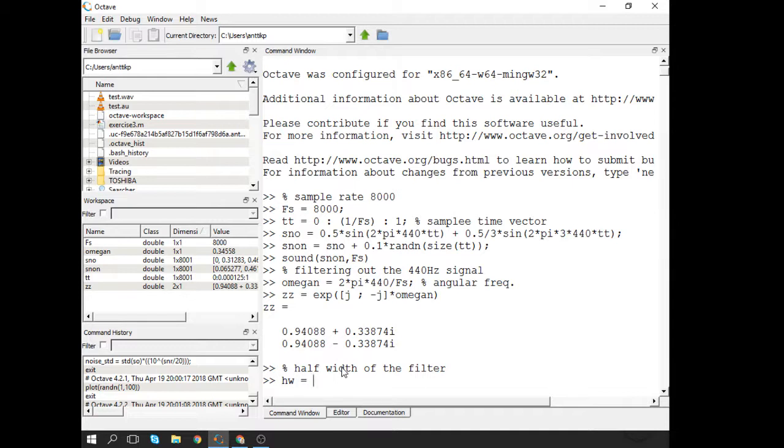Then we don't want to mess up with the harmonics at least. So let's put just for fun 50 hertz there and see what happens. Yeah, 100 hertz to make a point, since when you put it closer to the unit circle, then it doesn't show up that well on the zero pole plane.